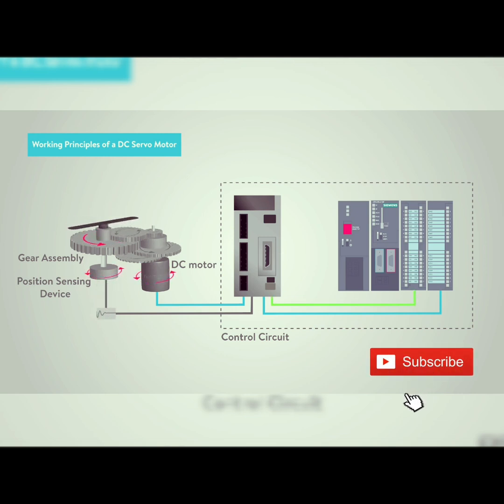The feedback signal sensor is normally a potentiometer that produces a voltage corresponding to the absolute angle of the motor shaft through the gear mechanism. Then, the feedback voltage value is applied at the input of the error comparator amplifier. The amplifier compares the voltage generated from the current position of the motor, resulting from the potentiometer feedback, to the desired position of the motor, producing an error of either positive or negative voltage.